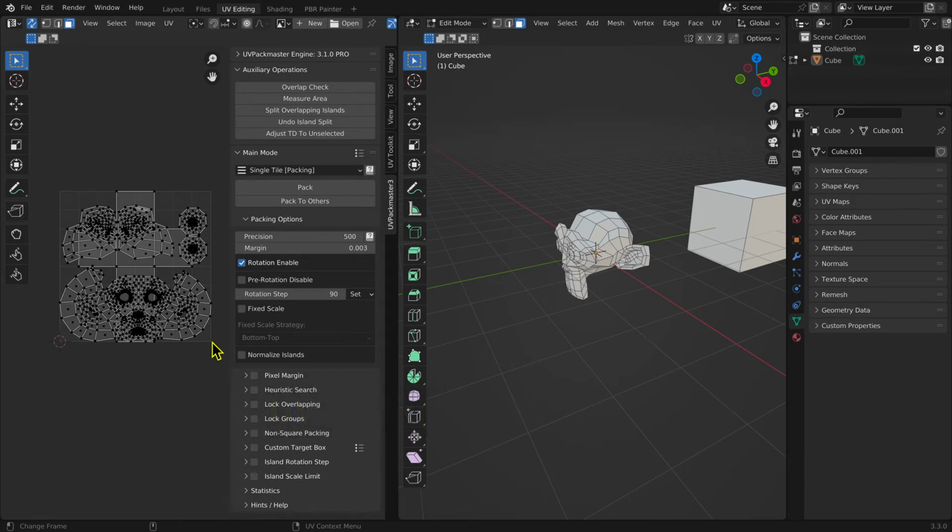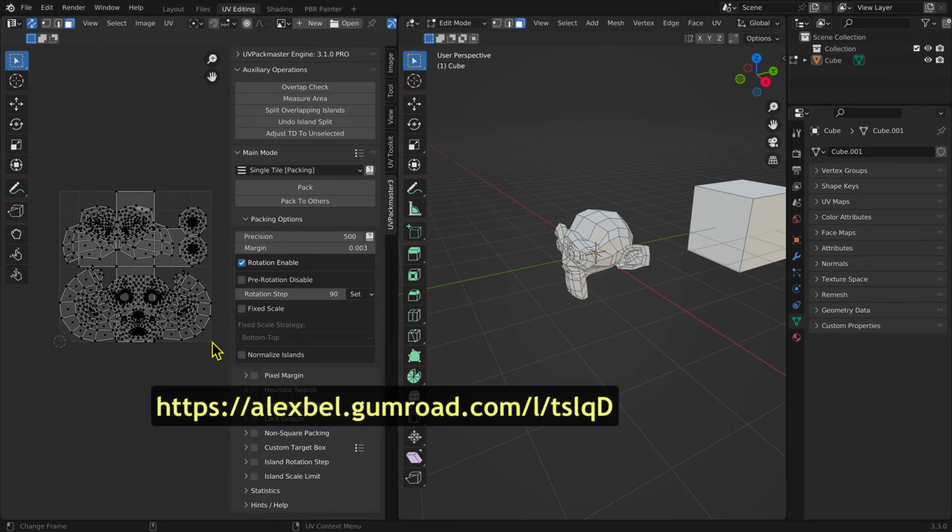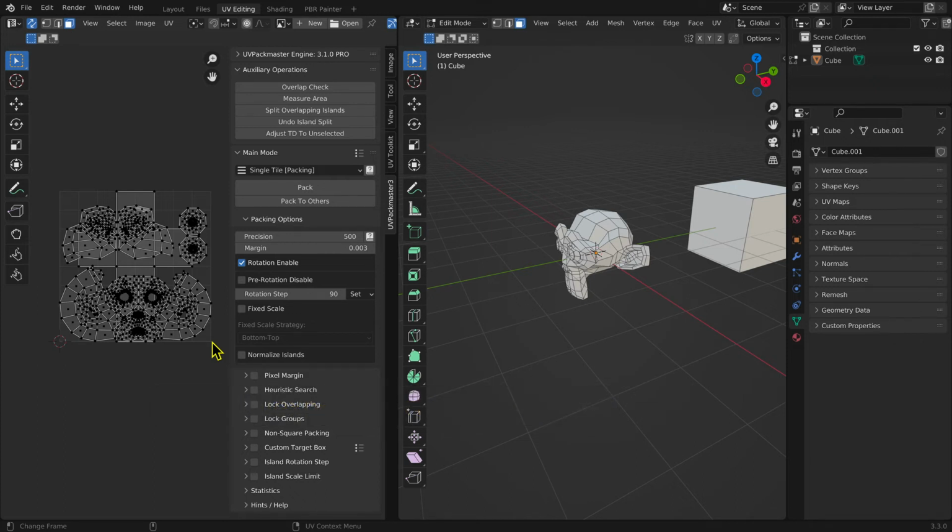The Blender add-on UV Toolkit has some functions that I like to use to achieve the best use of UV map space. In particular, I like UV Toolkit's ability to stack islands which are going to have the same texture applied. For example, Suzanne's eyes are identical islands. With UV Toolkit, it is easy to stack these on top of each other, and thereby use less of the UV map space for the eyes.